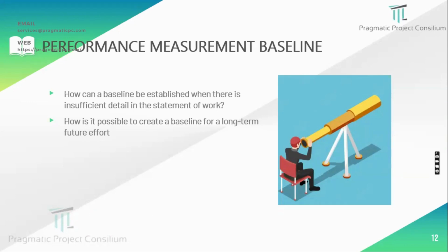Suppose any activity is required to be completed in a later stage of the project, but if very wrong logic is given in the relationship, it seems to be in the initial stage of the project. So ultimately we are performing that activity without knowing the right connection to the successor activity. It is a real-time scenario, and it happened in a few of my projects also.